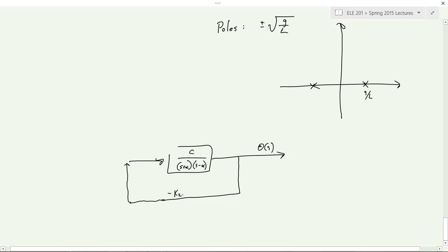Now, to fix that, we apply a second feedback here. We also do a derivative control. So we take a derivative of theta, and we add that in. Now, if you work out the algebra for what this allowed you to do, this becomes negative k4 in our software. This gives you another degree of freedom. Rather than just one parameter, that parameter allowed us, when you work out the math, to move the poles in and up the axis. This parameter is going to allow us to shift both poles to the left if it's chosen correctly. Okay, so it's actually going to be very stable.